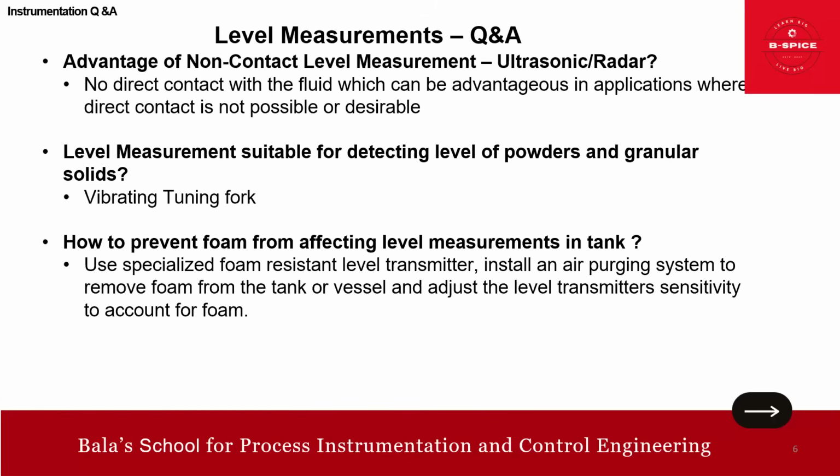Then, how to prevent foam from affecting the level measurements in a tank? Yes. If there is a foam application, then we can use a specialized foam-resistant level transmitter. Nowadays, we have all kinds of measures for controlling foam. That is one aspect. Then the other option is to install a defoaming system to remove the foam from the tank or the vessel. Okay.